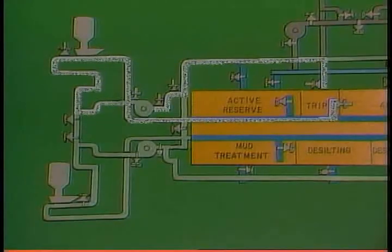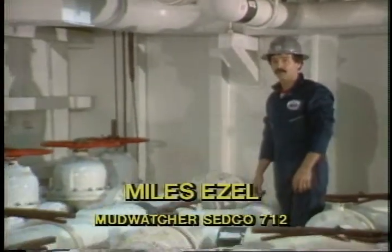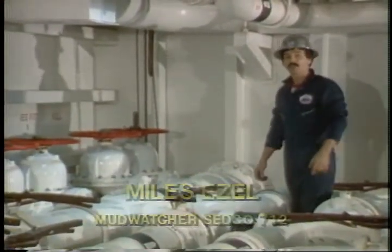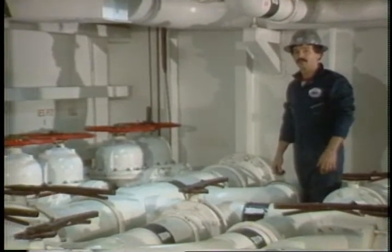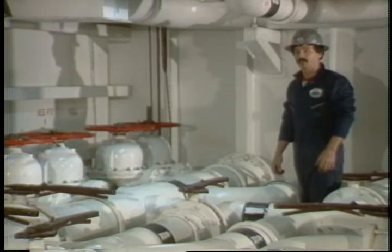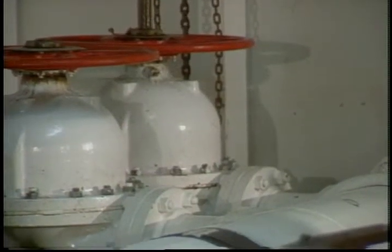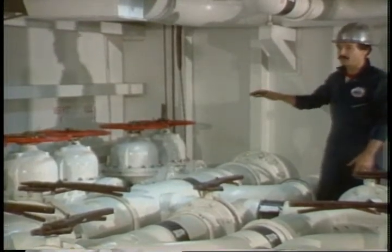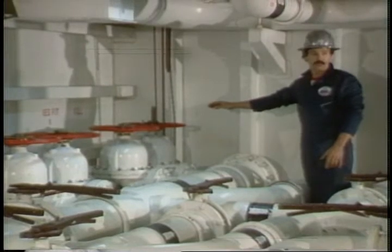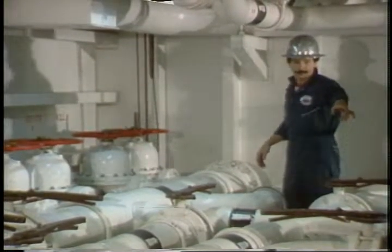Now let's watch someone do the same thing on our system. After getting the weight material over to my surge tank, now I'm going to have to weight up my kill pit to get a pit of kill mud. I have my suction valve open with all the other suction valves to the various pits closed. The pump I'm going to use is mud mixing pump number 1, which is located right here.